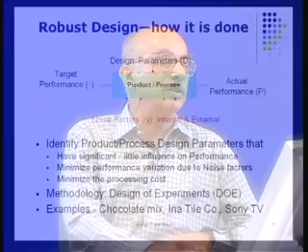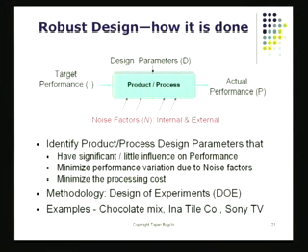What we are looking for is not only the mean performance or the average performance, we are also trying to look at what we call the variance. And this variance is the variance in your response or the actual performance, and this can be impacted by environmental factors. The goal of robust design is to make sure that the design is insensitive, basically, to the impact of this noise. If you look at a system, you have what we call design parameters. We've got certain target settings that we have to set. Then you've got these noise factors. Then you've got the actual performance.